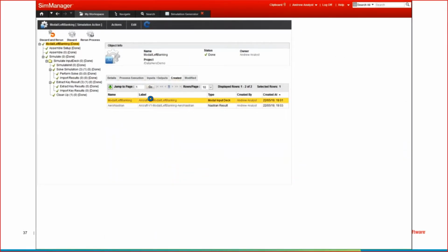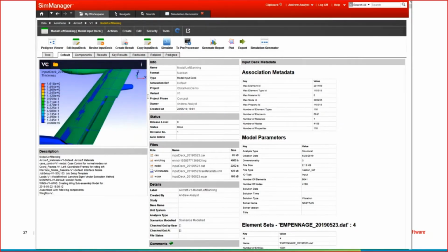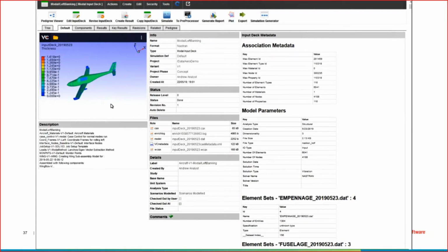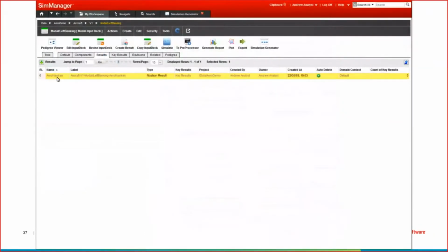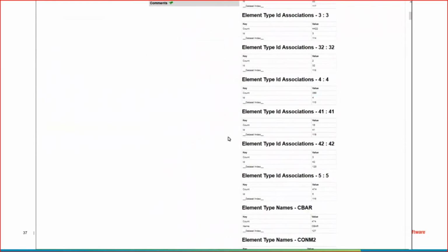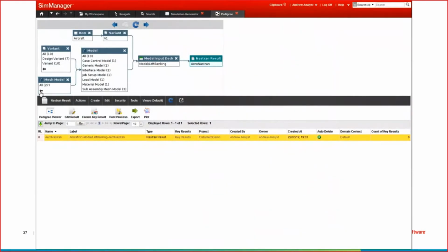And then from here, you can see that this is our input deck, which is now created. You can see the ailerons are in the right position. And if we zoom in, you can see that they're angled either to a flap up or flap down case, depending on whether it's a banking left or banking right use case that we're actually working with. So there's a correlation between the positions of control surfaces, correlating that with loads, and also then the subassemblies for the submodels themselves.